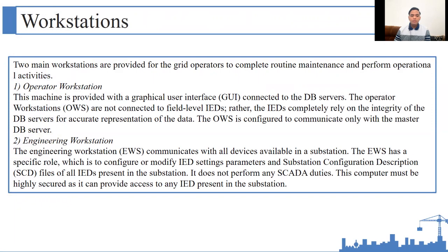The operator workstation is not connected to field level IEDs, rather, the IEDs completely rely on the integrity of the database server for accurate representation of the data. The operator workstation is configured to communicate only with the master database server.